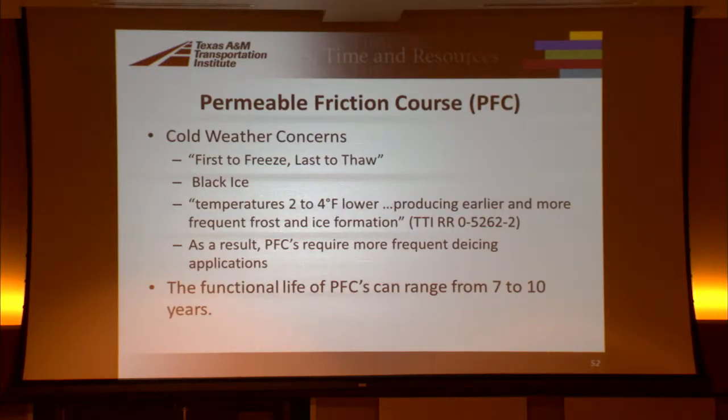In Fort Worth, though, I think this is still the case. We hadn't used PFC since we did that first round of plant mix seals. We did do something similar to what was built now with latex and fibers and open gradation. But one thing I learned at the department is you should always listen to your maintenance supervisors. In Fort Worth, we may be in a range where we have a considerable number of freeze-thaw cycles and a high enough humidity that every time you saw ice on your windshield, there was a black ice problem on a PFC somewhere.